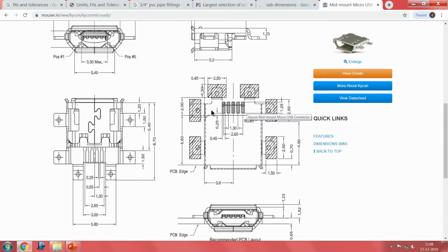There is a dotted line here, and then you see here there is a, this is called a chain dotted line. Typically a chain dotted line represents the midpoint between two. So if you take the total weight, this is approximately at the midpoint, and they have avoided tolerancing because this is a contract document. It is for you to go and purchase it and then use it in your design.